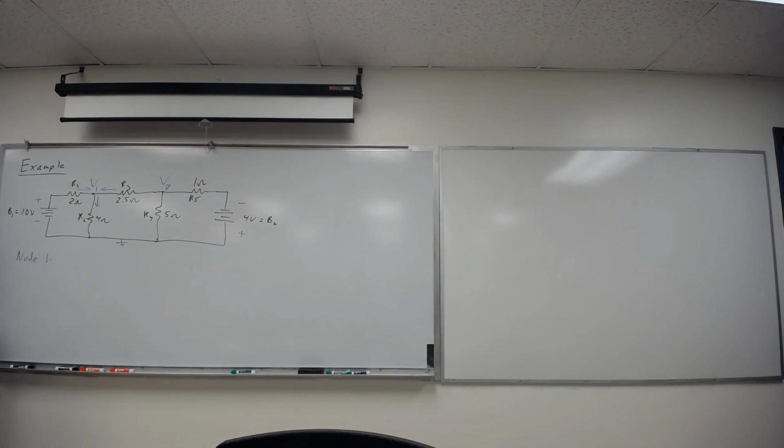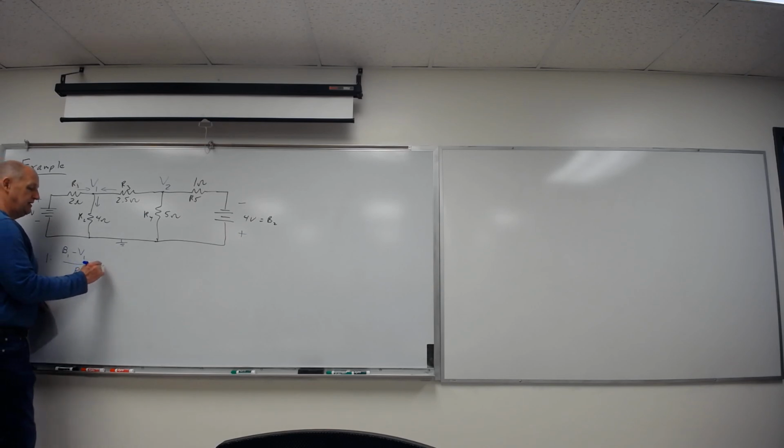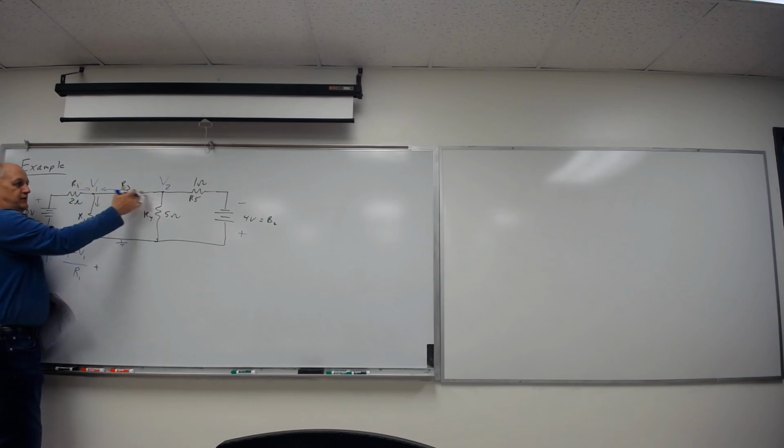Okay. So, the current that flows in here, if I look at Ohm's law, will be the voltage across this resistor divided by the resistance, right? Which will be the voltage of battery 1 minus whatever's there divided by resistor 1. I'll put values in, but I just wanted to do this generic to start with. So the voltage across here is going to be this voltage minus that voltage divided by resistance 1. The voltage into here will be this voltage minus this voltage, the voltage on the two ends.